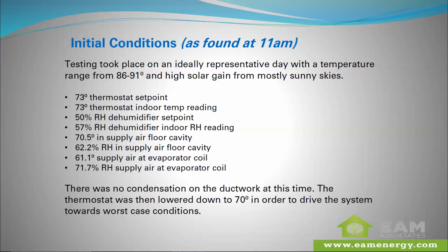The standalone dehumidifier that had been installed in the home was set at 50% relative humidity and was reading 57. What I am calling the supply air floor cavity, guys, is that interstitial cavity between the first and second floor where all the ductwork was located. When you see me call it the supply air floor cavity, that's what I'm talking about. And we're putting temperature probes up in there.